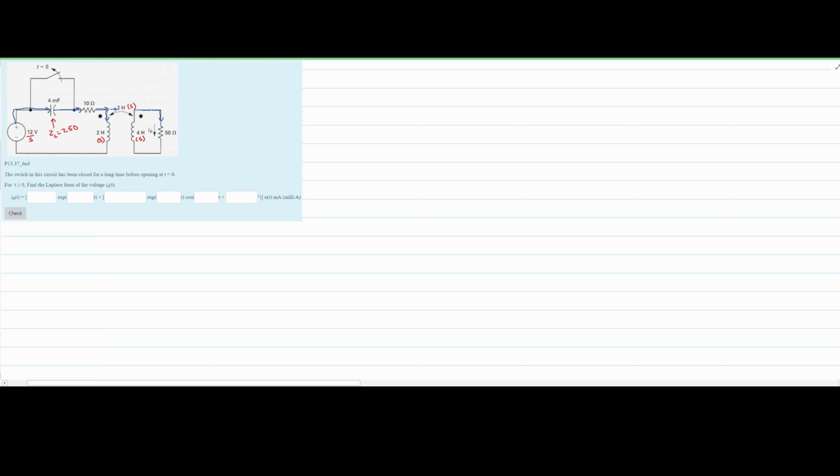We know that there's some voltage over our inductors, so we'll call this plus, minus V1, and this one here, we'll call plus, minus V0. And there is an important dot convention. This is in section 11.9, I think, and has to do with mutual inductance and dot convention. Basically the way the current flows away from or into the dot determines the sign of our voltages and later our currents dealing with the inductors.